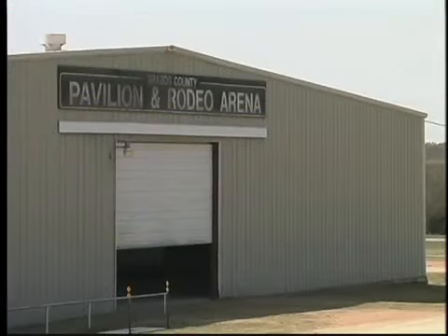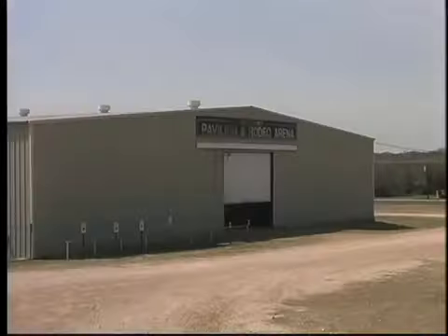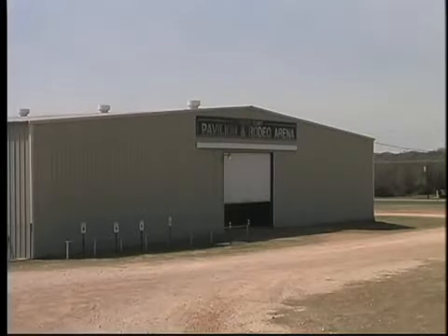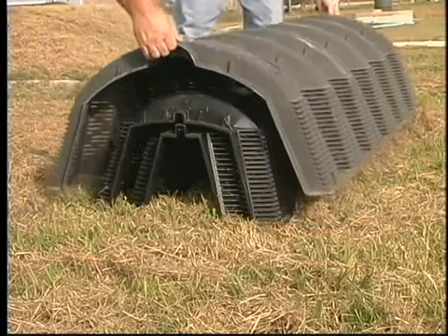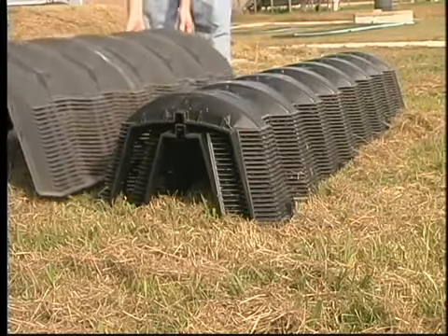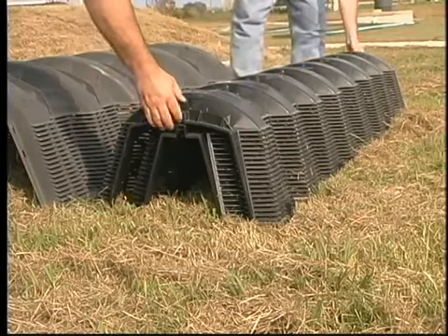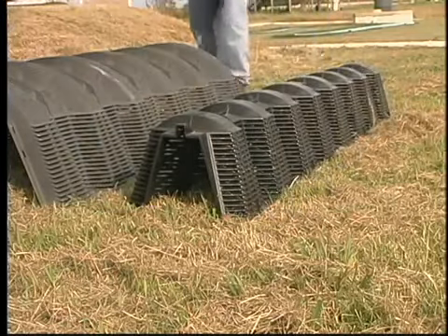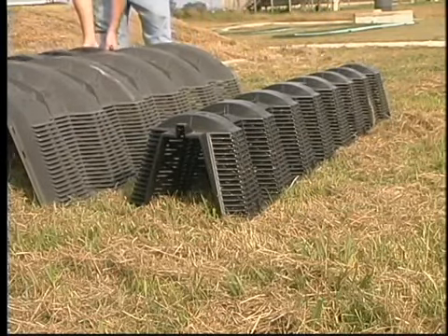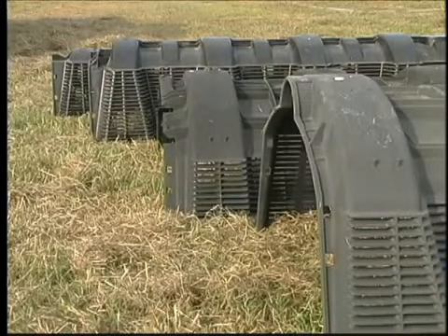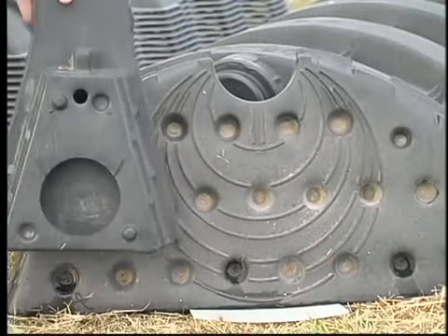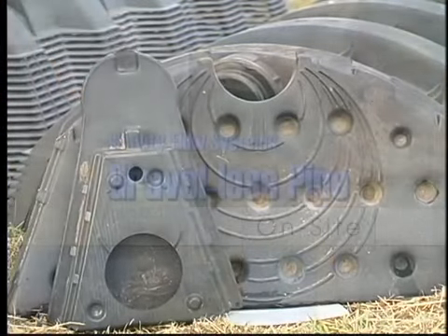Leaching chambers can also serve as reservoirs for facilities with intermittent high-volume use. The components are available in a variety of sizes and have connectors to allow construction of trenches to follow the contour of a site. However, you should be aware that maintenance and soil requirements for this system are quite similar to that of the media-filled trenches. This, too, is not a good option for soils with high clay content.